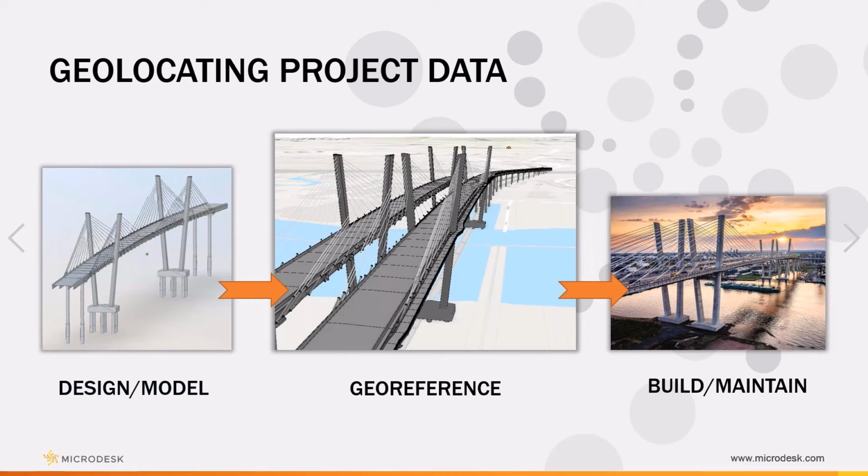Now, if that data is not assigned a location from the Autodesk side, it must then be georeferenced within ArcGIS Pro. Once we're at a point of having a model whose level of detail fulfills our need and whose location is defined, we can then package that layer and publish it as a scene layer package to be hosted in the GIS, where it can be dashboarded, integrated with GeoBIM, and much more.